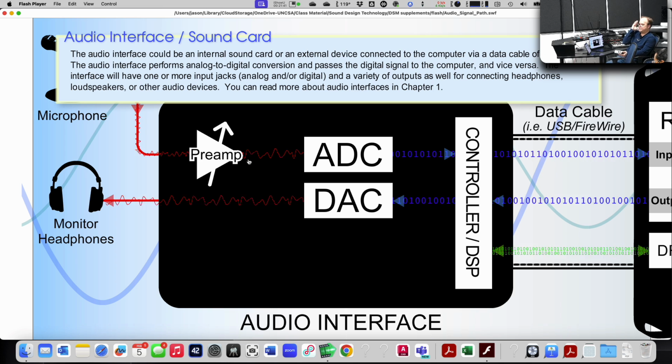Like, you can't just say nothing beyond this will pass. There's a ramp. There's a tail to those things. And the quality of that filter is a big part of what makes the converter considered to be a good converter or a good interface. And so the ability to sample at higher sampling rates really just is more like accounting for the imperfections in that filter, because some of those higher frequencies are still getting through, even though they're trying to get filtered. They're just quieter.